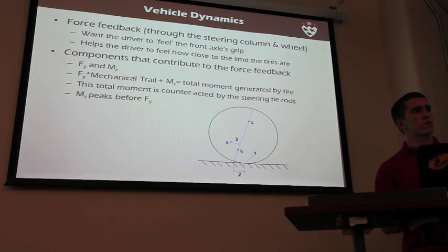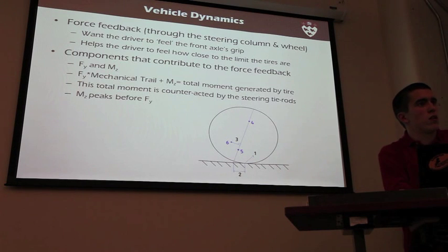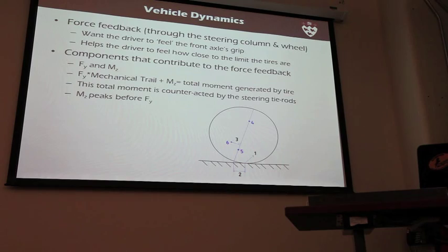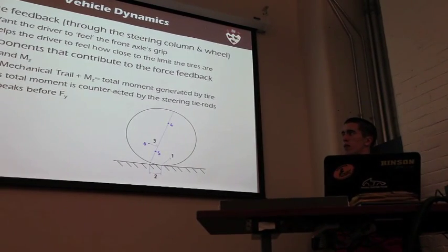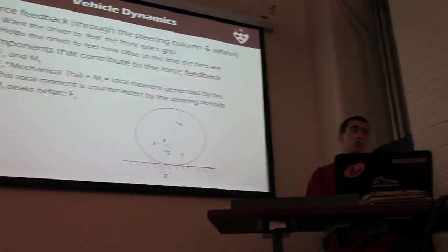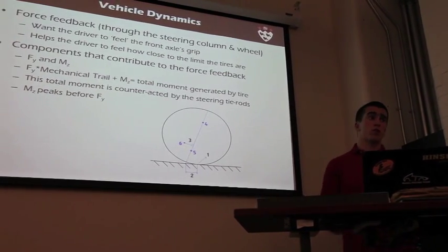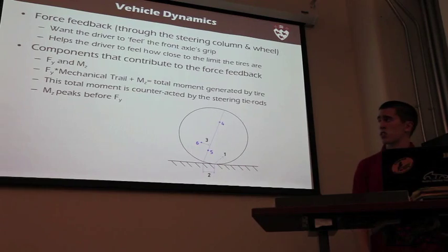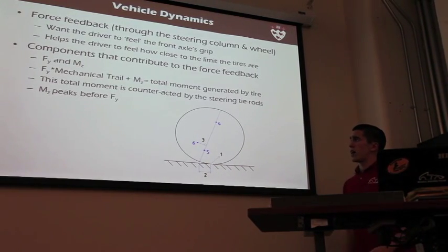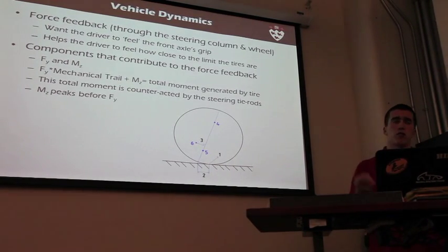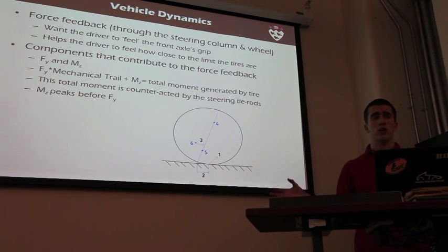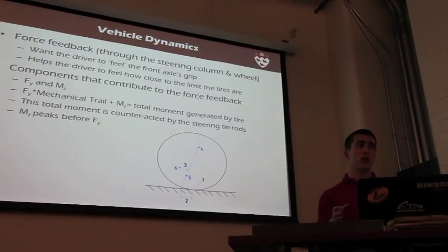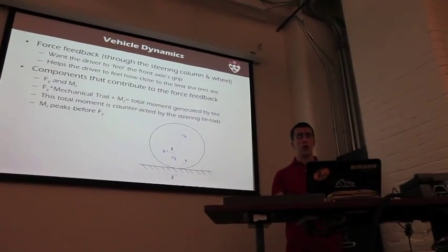Yep. I know it wasn't included, but do you know how power steering works? Yeah. Basically, power steering is just hydraulically actuated. That's more in bigger cars, because our car is pretty light. So just by adjusting the mechanical trail, you can get fairly good steering feedback. The steering feedback in our car is higher than a normal car would have.